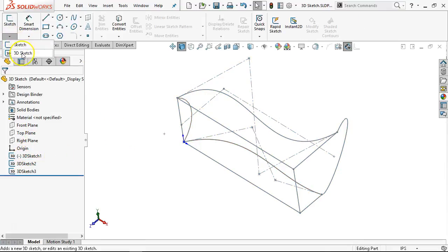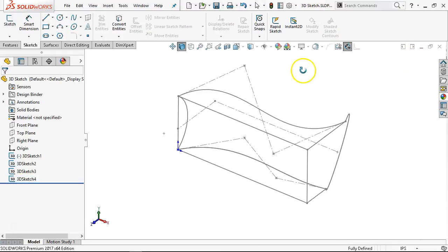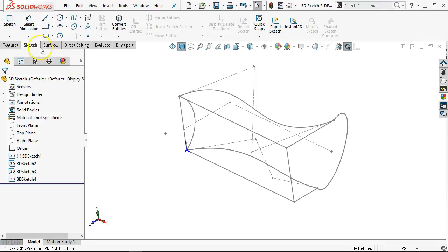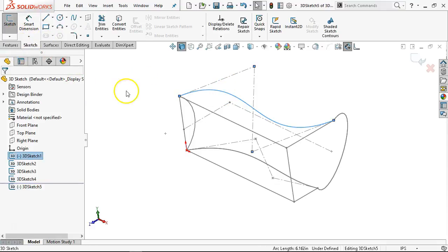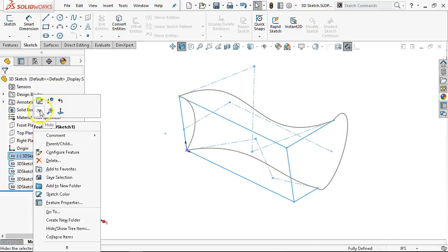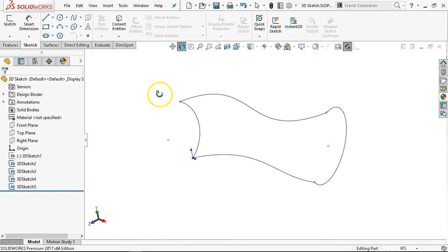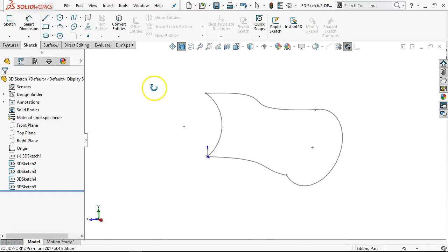Back into the 3D sketch. Convert the entities one more time. All right, so now we'll go ahead and generate it, see what we get for the sweep and the loft. We'll need them all eventually anyway. And convert, and then we can hide the first. All right, so that is the geometry that we're shooting for. This transition here, I expect that to be the most difficult.